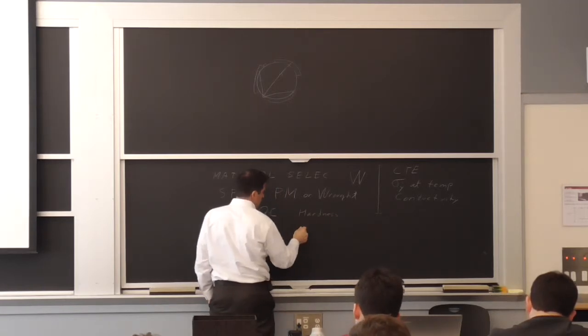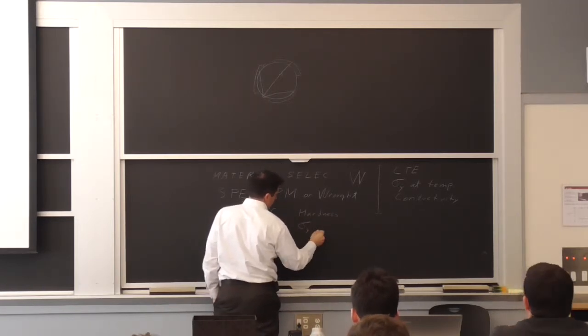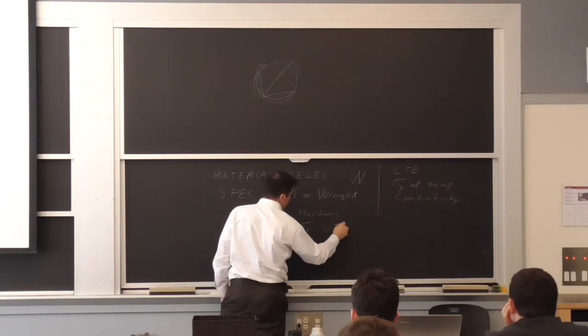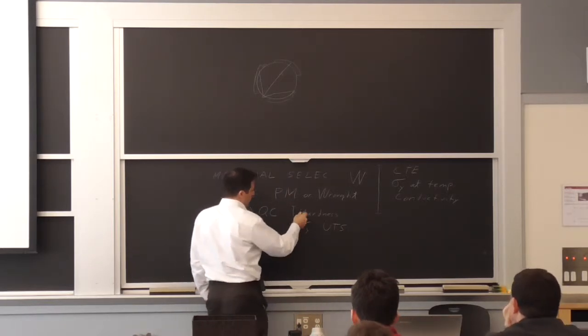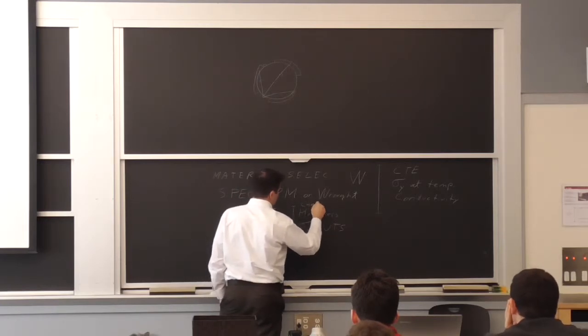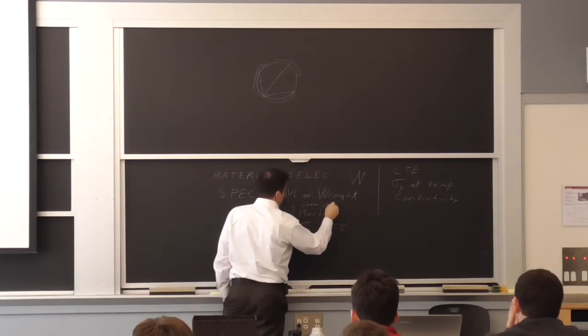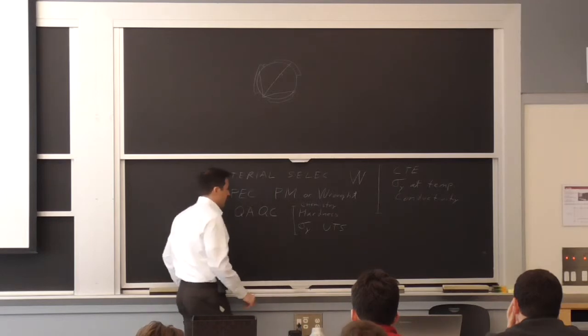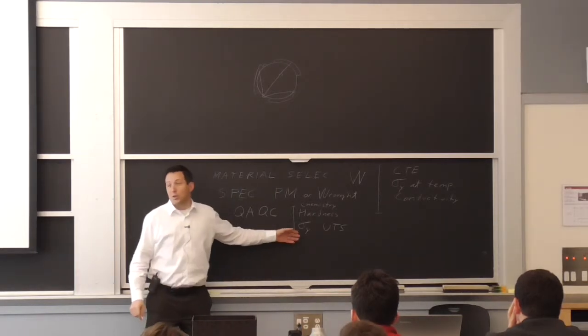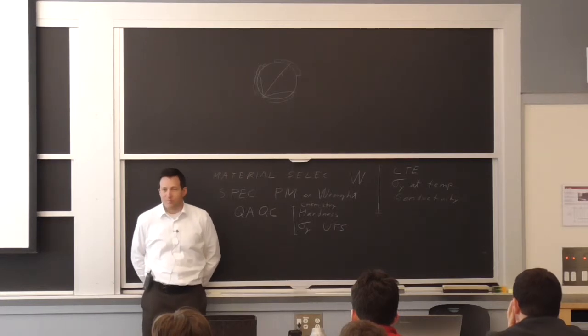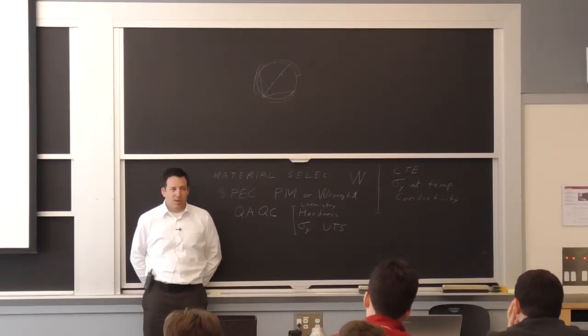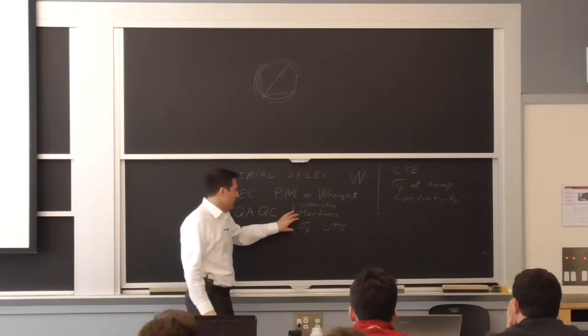I can also do a tensile test that's going to give me my yield strength and my ultimate tensile strength. These are really nice. I can test for chemistry. Now, one problem is, what temperature am I going to do those at? It turns out they were just doing ambient temperature, which means they had no idea how